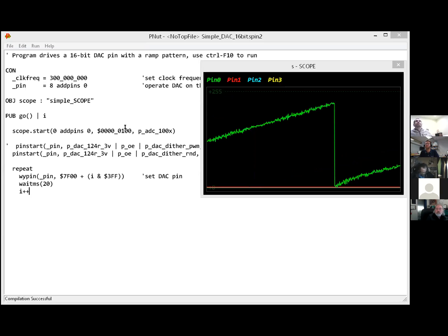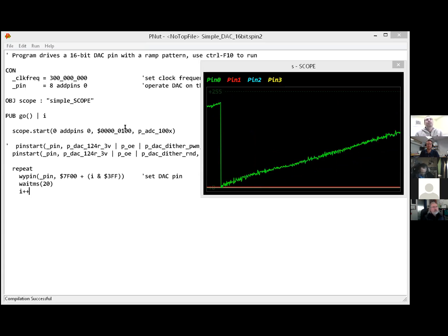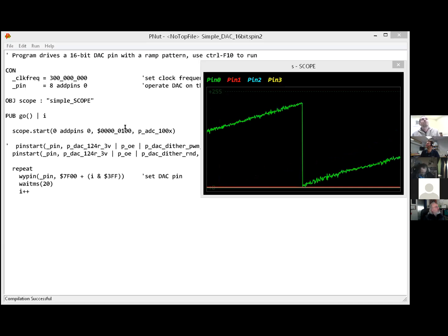Is that noise a normal distribution? That you're seeing on the screen right now? Yeah, it looks like it probably is. I mean, these are just samples that were taken at discrete points in time. If they were averaged, that thing would look way cleaner, but it was just a sample that was taken at some point in time and they were all put together. And then that thing only has about 6 bits of DC resolving power. So you should expect to see 1/64th of full scale, you know, just noise. I see. That's about what we have there probably.